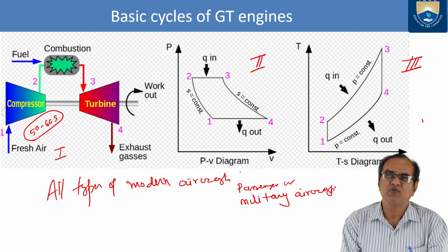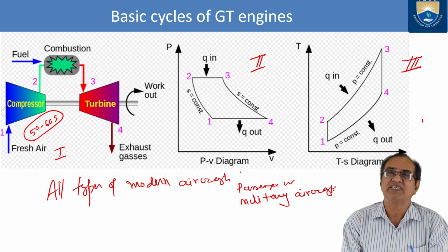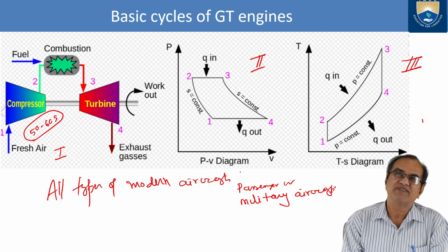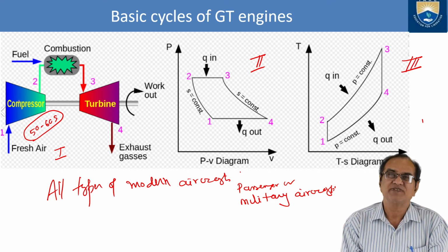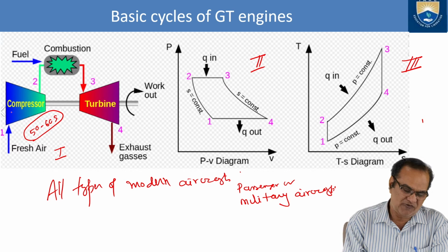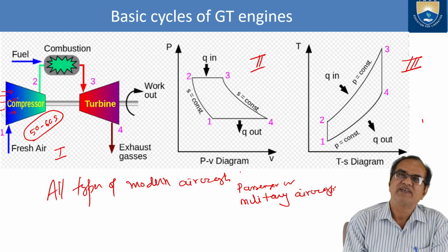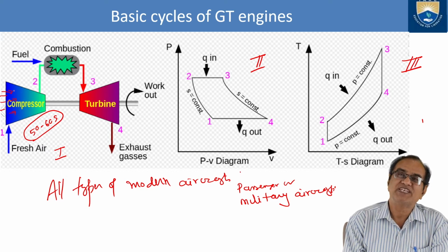It may be 2 stages, 4 stages, 5 stages, 17 stages, up to 20 stages I have seen as per the type of engine. And in every stage, air is entering from here, and in every stage the pressure ratio is increased by nearly 1.2.